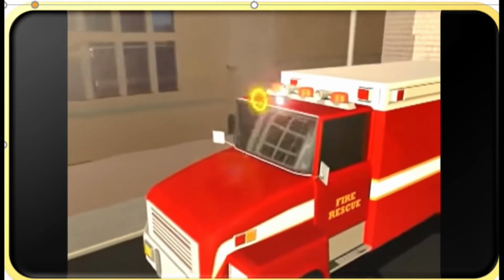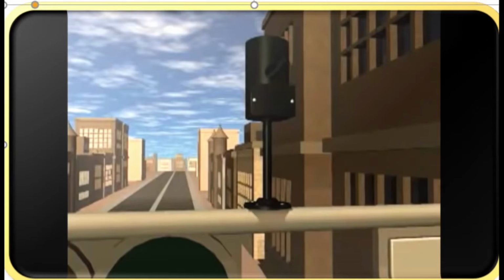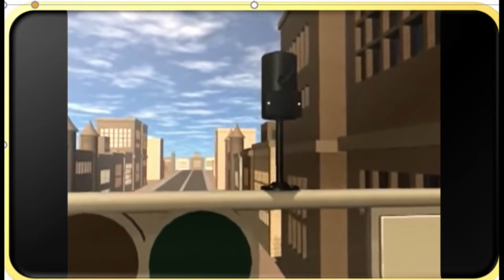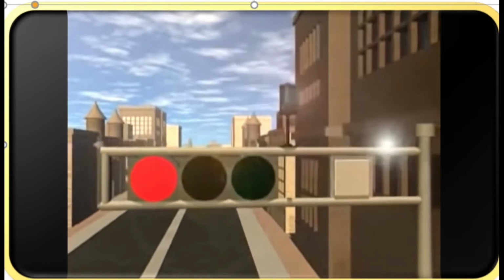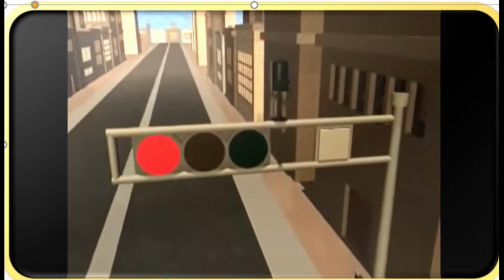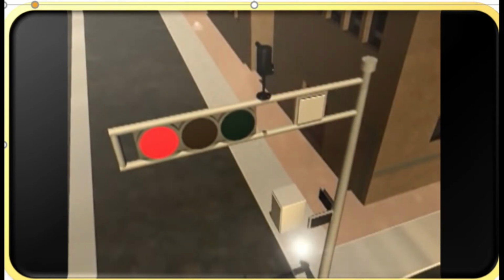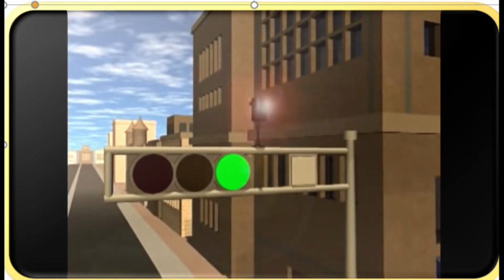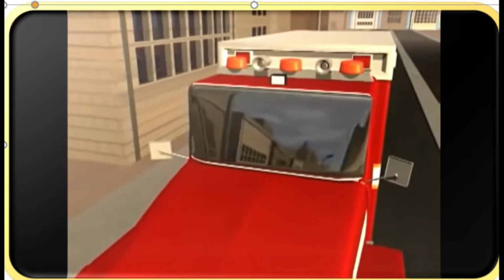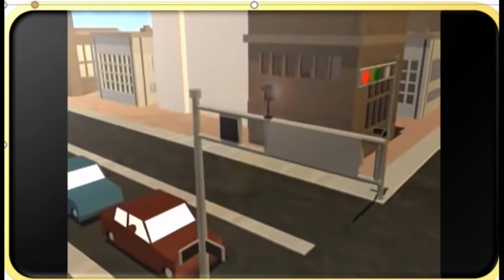Transmits secure data in an optically encoded signal using the infrared emitter. The detector receives the transmitted infrared signal, turns it into an electrical impulse, and sends it to a phase selector located in the traffic control cabinet. The phase selector works with the signal controller's normal operation to cycle to a green light for the oncoming emergency vehicle. Traffic responds naturally. Cross-street traffic stops, and traffic in front of the emergency vehicle clears.